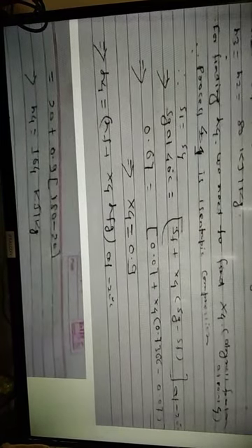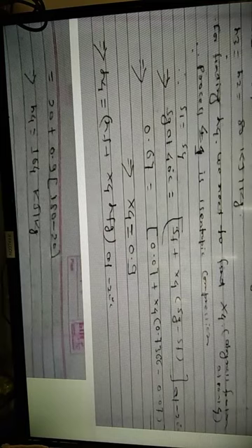So we simply have to put in these values, SG and SF: 0.7366 minus 0.07, and from this X4 is calculated. X4 is equal to 0.9. So the dryness fraction of the refrigerant at the exit of the evaporator we have calculated, and this is 0.9.